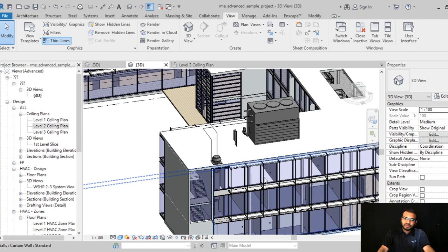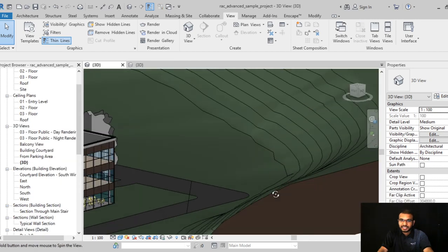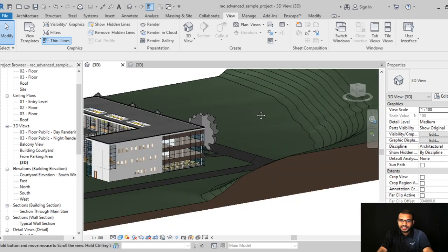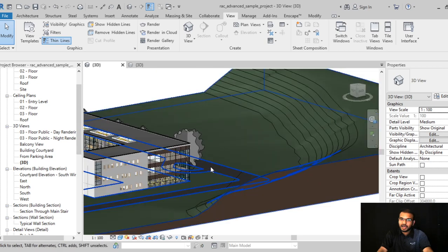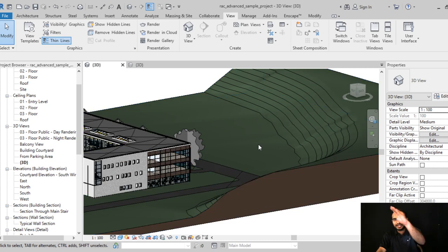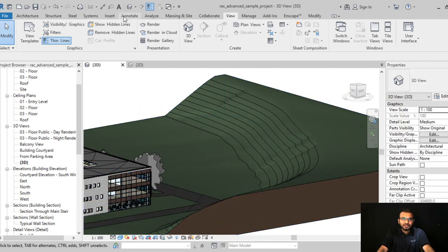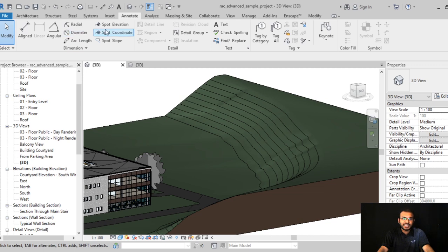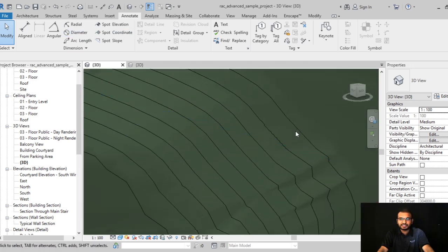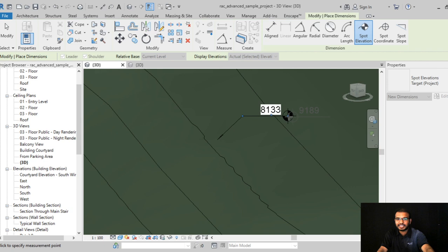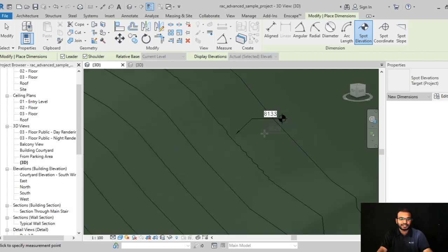So this is what you need to understand when you are dealing with whatever items are available in the project. This is the site, where your building is going to be constructed. Whatever services you need to run under the site, and how you need to make the gradient of the site properly, everything is maintained from there. And if you want to find a height, say I need to find the height of this point, you can go to the spot elevation option and directly catch the height at that particular location.